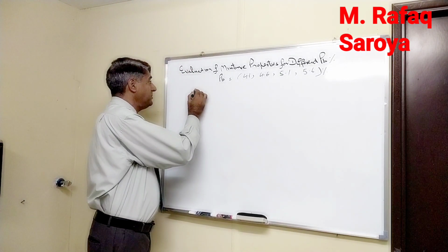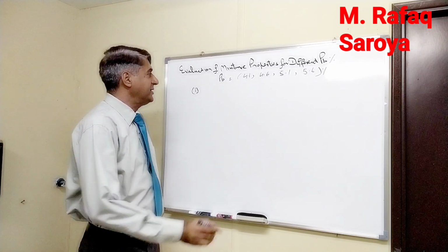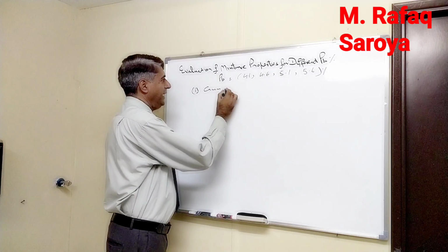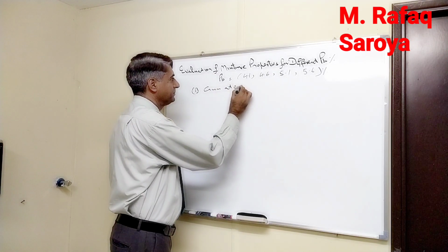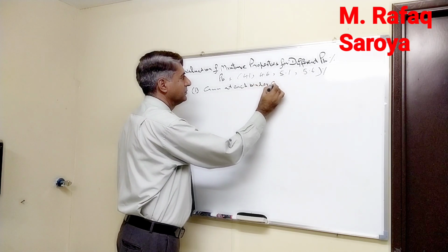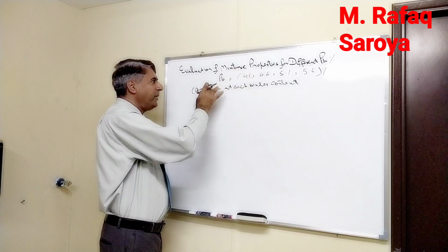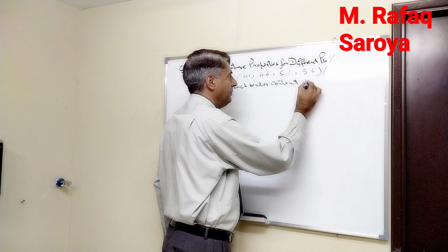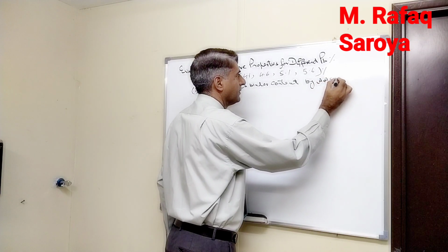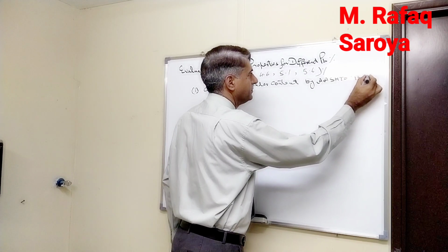First property, which is very mandatory for the development of the mix design, is GMM. At each binder content, we will determine this GMM by AASHTO T209 method.